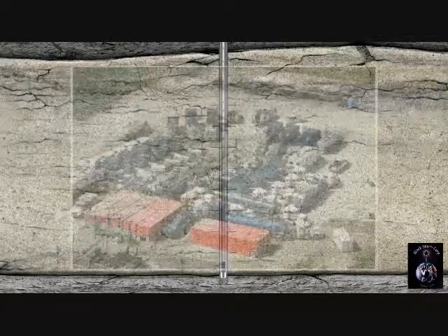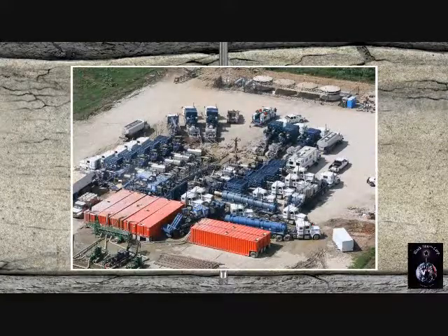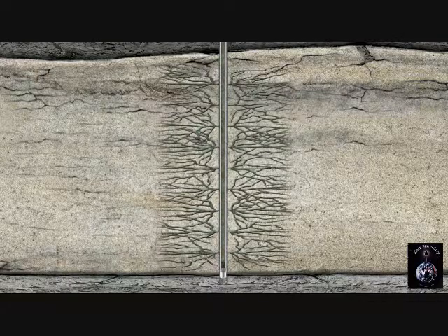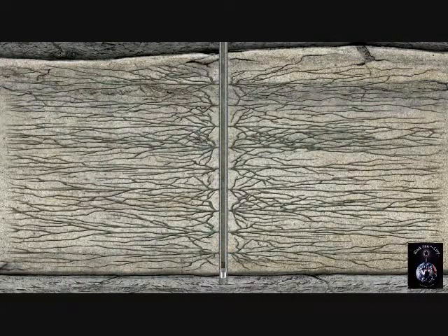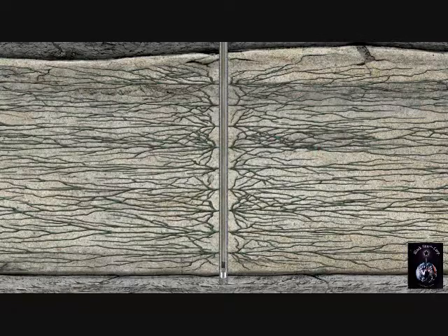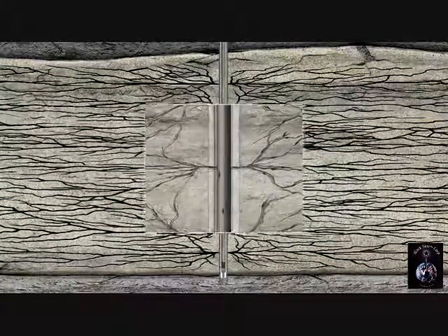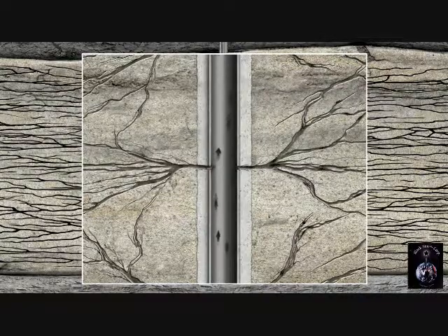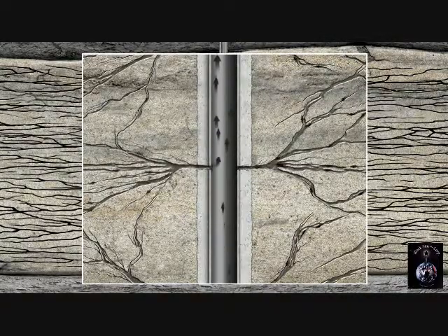The next step is to hydraulically fracture or frac the zone. Here, sand or other proppants are pumped into the wellbore under extremely high pressure. When the mixture reaches the target zone, the pressure forces it out through the perf holes and out into the sandstone formation, causing it to fracture. This creates a fairway connecting the reservoir to the well and allows the released oil to flow to the wellbore.